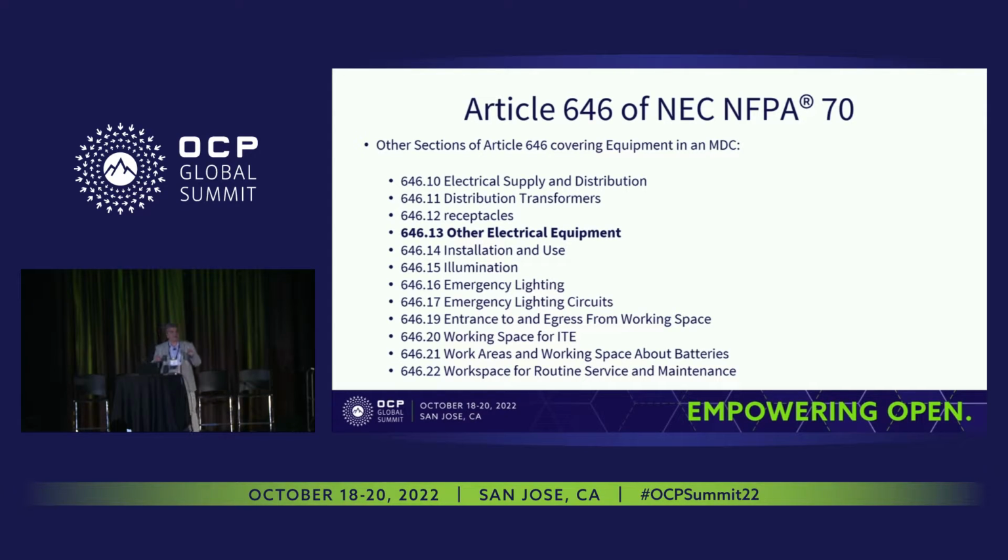So one thing that I didn't say before when we talked about a definition: the National Electric Code considers modular data centers as structures, very similarly to your brick and mortar structures. They are fixed structures, they're not movable. Once they're installed, they're permanent, and decommissioning is a long process. It's not something where you can bring a truck and lift it up. Therefore, all these sections will refer to the other sections of the NEC code, and you have to comply with all of them.